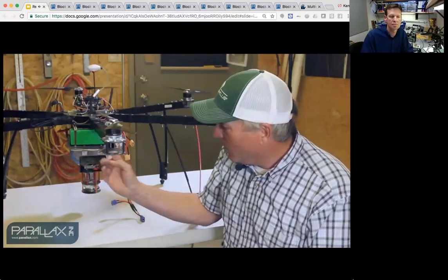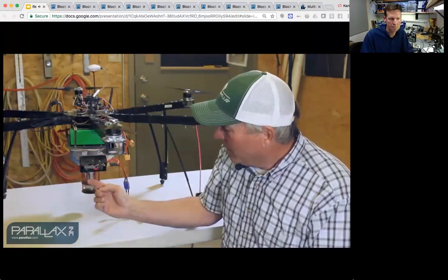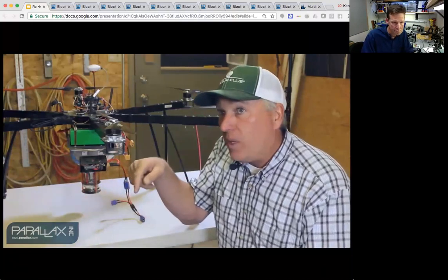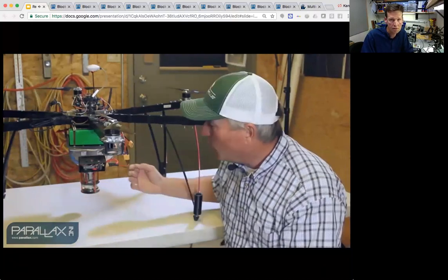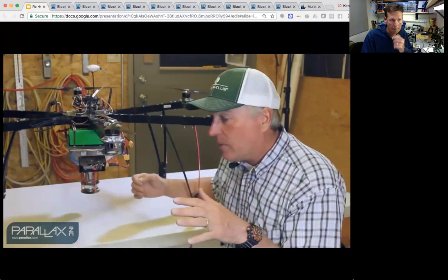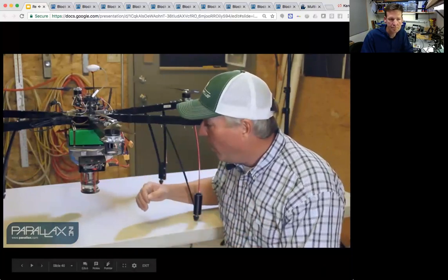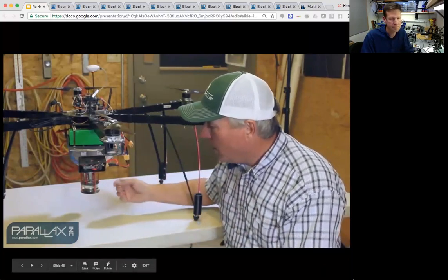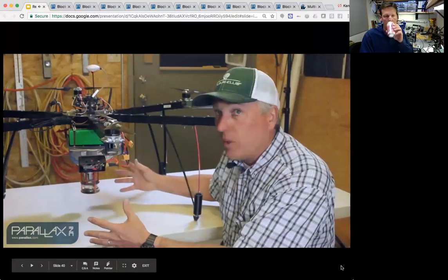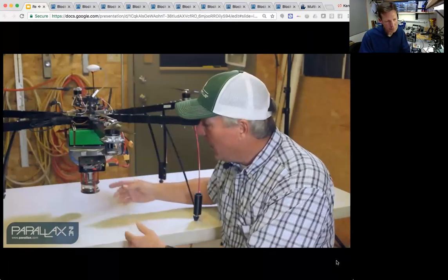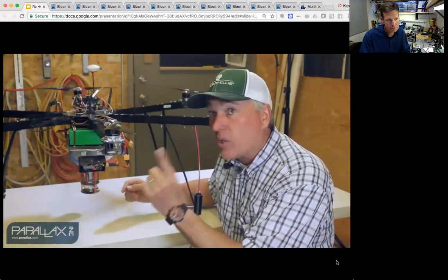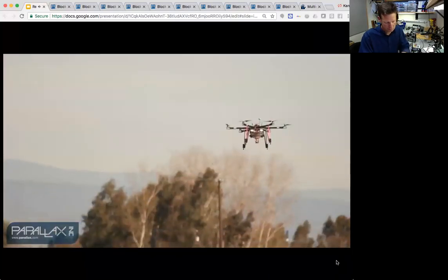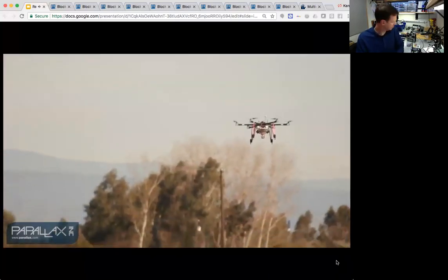So it turns on the slinger, it opens the trap door to the auger feed, so there's no loss of material. So what happens is we get to where we're going to pollinate over the top of a row. The spinner turns on, which moves the pollen out towards the vortex of the blades. The trap door opens, and then the auger starts to turn. We set a predetermined ground speed.